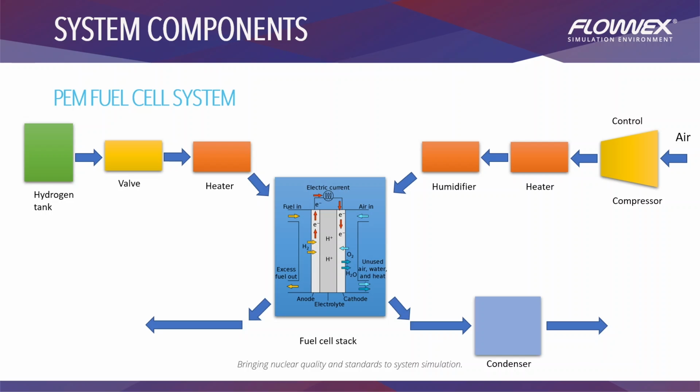However, it might not be sufficient for the polymer electrolyte membrane to operate efficiently. A humidifier is added to the network to control the water content at the cathode side. When the overall reaction of the fuel cell occurs, water forms, and thus more water will exit the cathode than the water entering it. A condenser is used to cool down the airstream, allowing for the water vapor to condense. This liquid water can then also be used in the humidifier and the rest be discarded to the atmosphere.